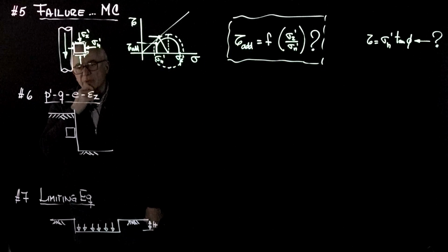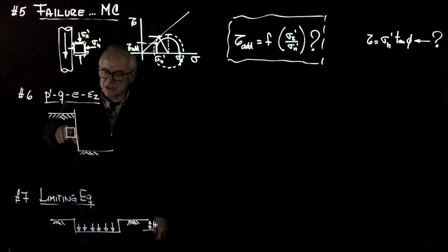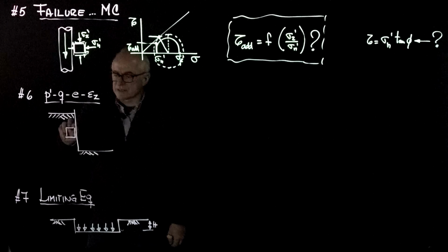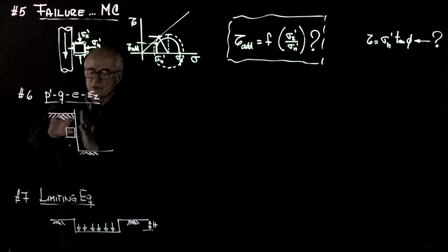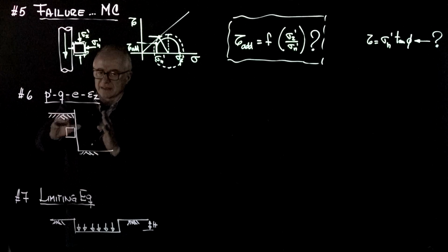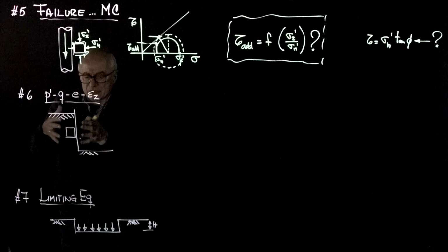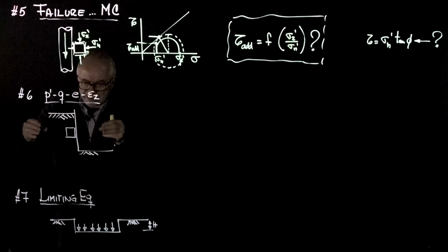The next problem is a problem of low deformation and volumetric changes that this element will experience if I do an excavation and then allow it to relax laterally. So this is a lateral unloading, there will be lateral extension from a point of view of the geometry of the element. It will get shorter and fatter.